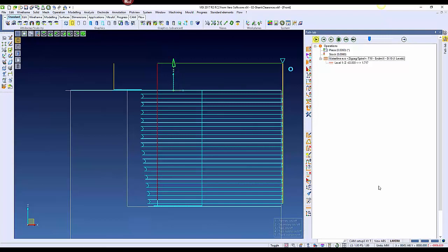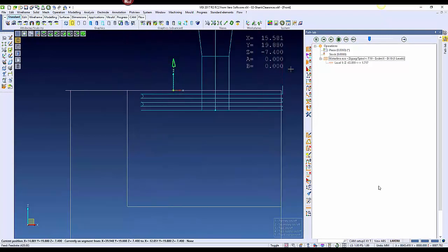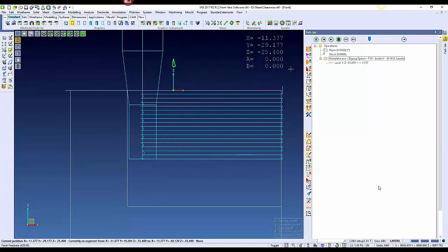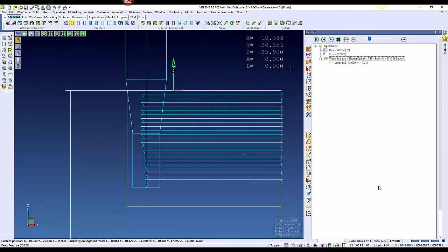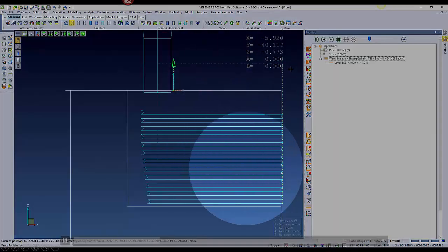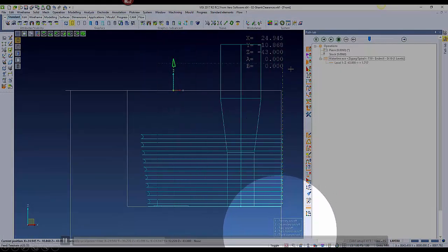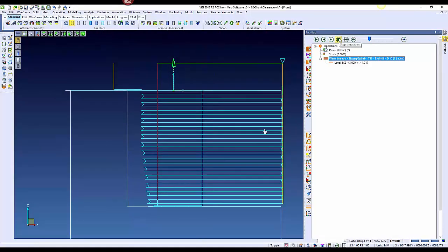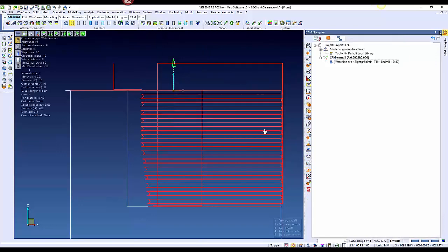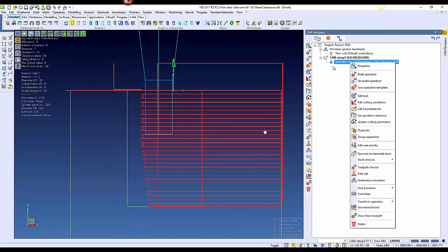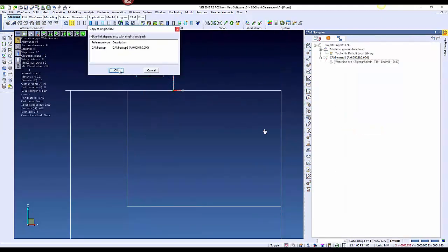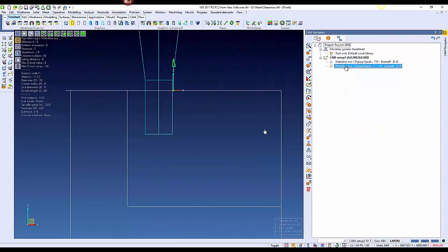Once again, we're playing the toolpath, and we also have our tool holder and our tool on, which is 3 and 4 on your keyboard. It can be seen down here as well, tool 3 and 4. So let's open up the properties of that Waterline Evo. We'll first duplicate it so that we can see the difference when we adjust some things.